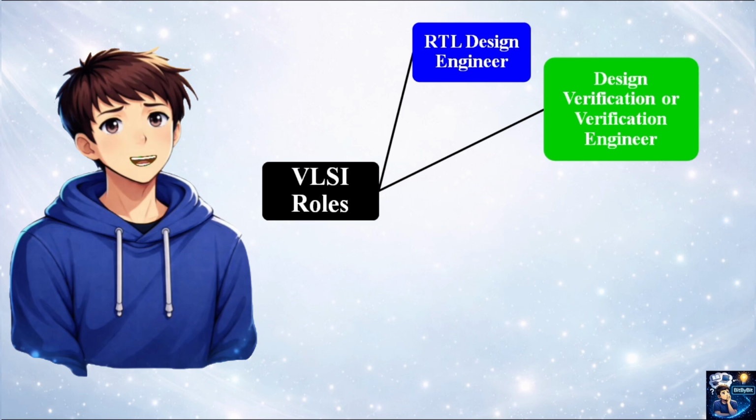Second subdomain is verification or design verification. Once the design is written, it must be verified to ensure it works exactly as intended. Verification focuses on checking correctness and corner cases. This stage is critical because the cost of fixing bugs increases exponentially as we move later in the design flow. A bug found early can be fixed in code. The same bug found after fabrication can require a costly respin, delaying the product by months and costing millions. That is why verification plays such a crucial role in VLSI.